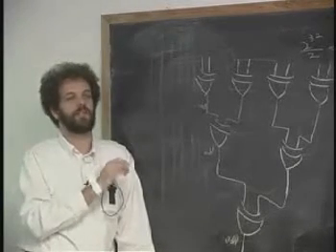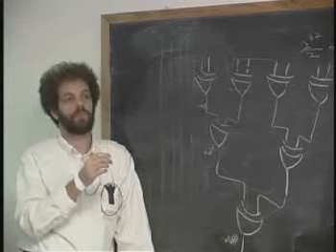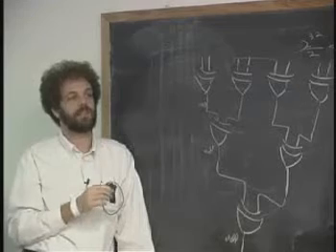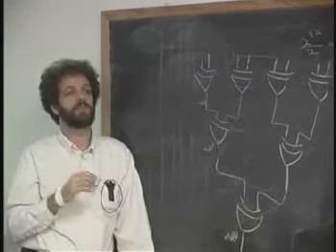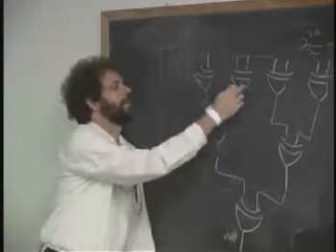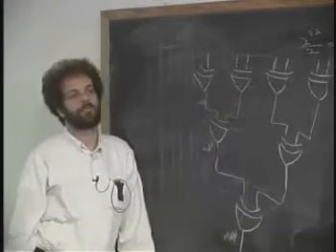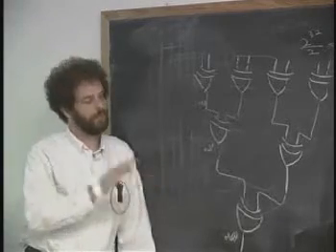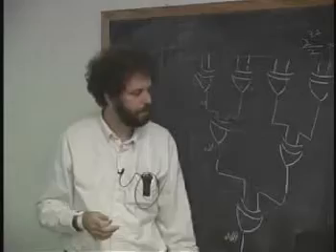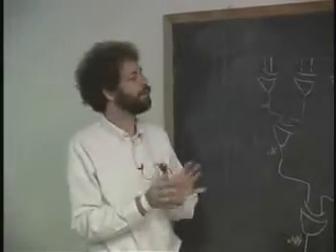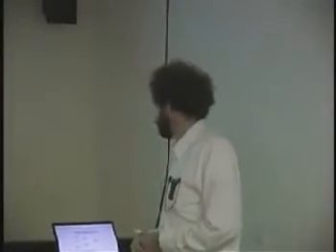Draw me the sum of products of 8 inputs. 2 to the 8 is 64, right? So I'm going to have 32 AND gates and an OR gate with 32 inputs, which is a huge structure compared to this one with 1, 2, 3, 4, 5, 6, 7 parts in it. Much smaller and much faster too. Okay, so the big message here is that Karnaugh maps and sum of products is good, but don't get fooled into thinking that that's all there is. Often there are other forms which are in fact better, depending on the function.